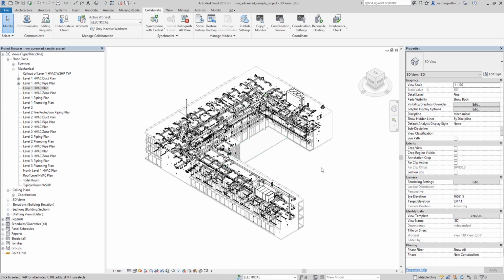From now on, you can tell your team members that they will now be able to create the local copy of the central file, just like what I showed you a while ago. So how to create a local copy? You just need to close the central file.